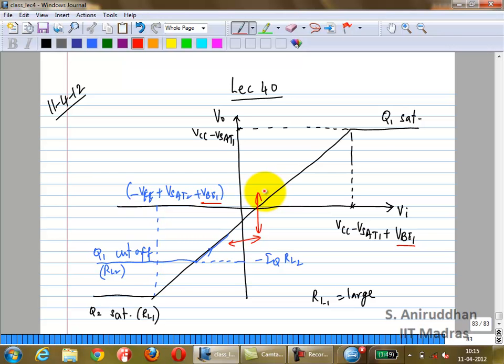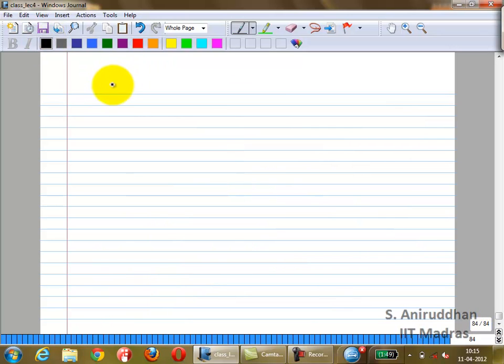What else? Gain is close to 1, so we already know that. Actually, in the case of the bipolar, it's almost exactly equal to 1 because you only have output impedance, which is usually much larger than your 1 over GM. Correct? What is the third parameter? Efficiency and output power, right? Both go hand in hand. So first let's calculate output power.